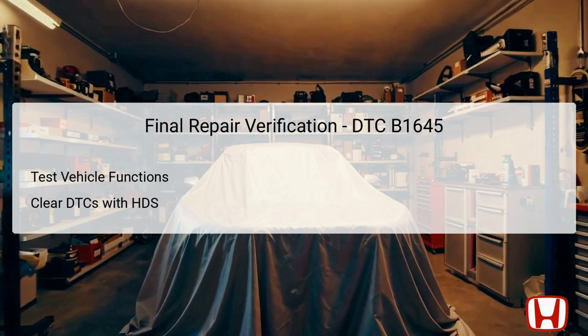This involves testing all related vehicle functions, particularly the keyless entry and any components linked to the driver's door. After confirming that all operations are back to normal, the next step is to clear the diagnostic trouble codes using the HDS. Ensuring that no residual codes remain is important, as it verifies that the issue has been resolved comprehensively.